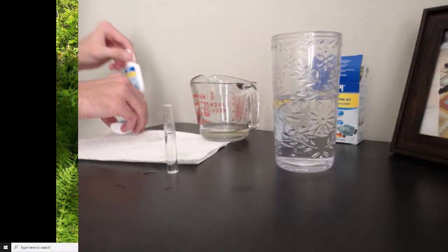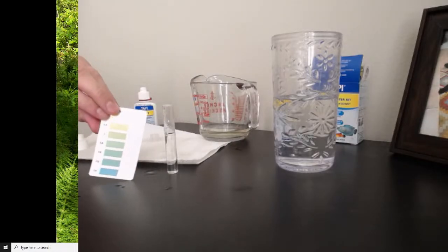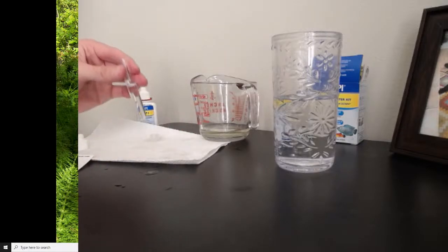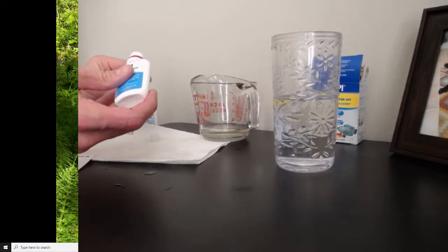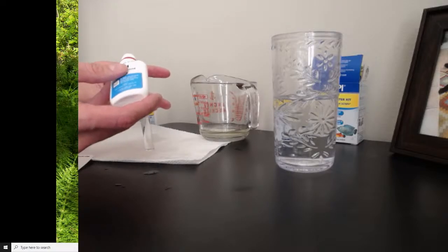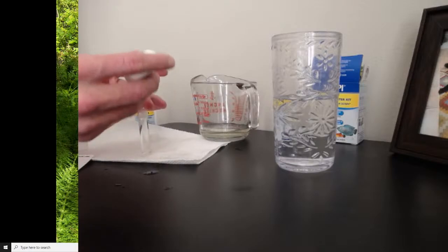So I think this is going to be probably a little bit above the scale for our pH scale again. Typically, our water distribution systems want to operate a little bit basic to avoid any corrosion of the pipes. We'd much rather have the opposite of corrosion, precipitation. So we'll talk about that later in the semester.